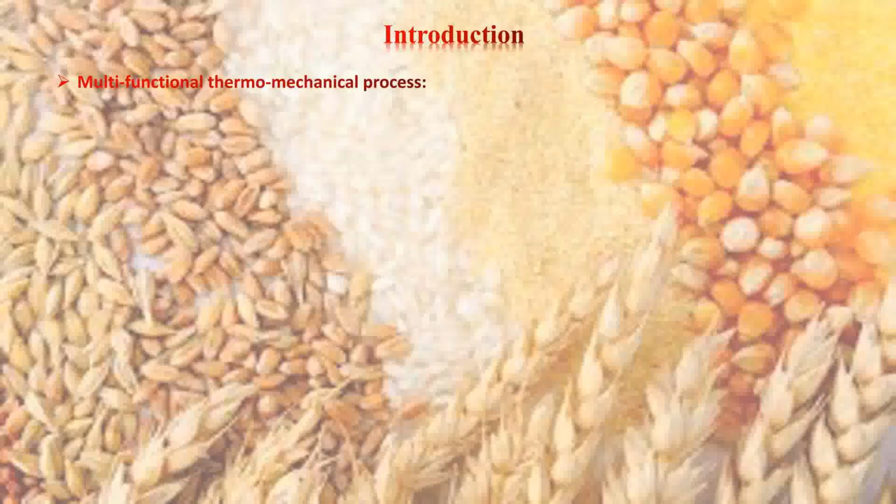As the phrase suggests, it's a set of processes. The first is mixing of all the procured raw materials from nature, which are subjected to the extrusion machine or the extruder chamber. The second process is shearing. Shearing means subjecting those premixed ingredients to constant pressure in extreme heat and temperature, or increased pressure in the compression section of the extruder chamber, so that all those premixed ingredients get mixed and homogenized properly.